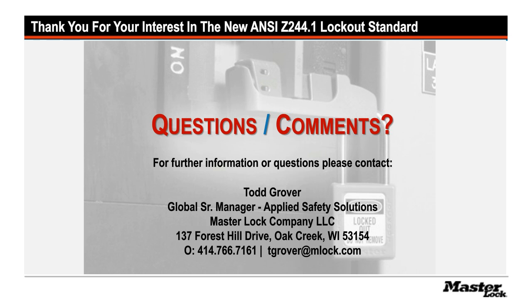When written auditing of procedures needs to take place, if you look at what has been established by OSHA over the years, they would like to see that on at least an annual basis, every lockout procedure that is in use be reviewed for accuracy and completeness and determined if any changes to the machine or equipment or process has taken place that should be then updated in the auditing outcome in terms of corrective action.